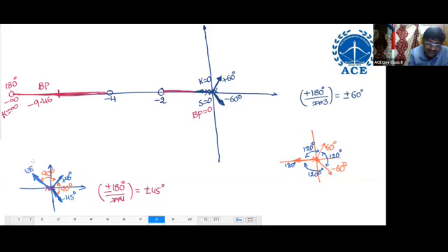Again add 90. Here also the same 90. So how much? 225 degrees. That means all the poles should leave from the point by maintaining equal phase shift.